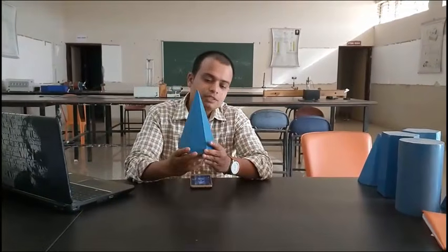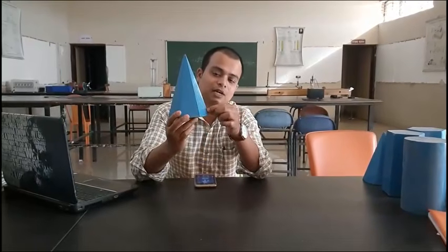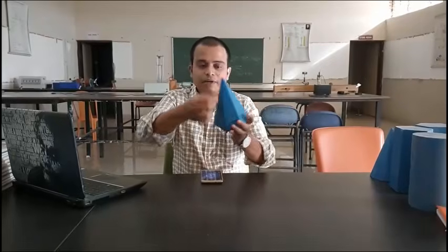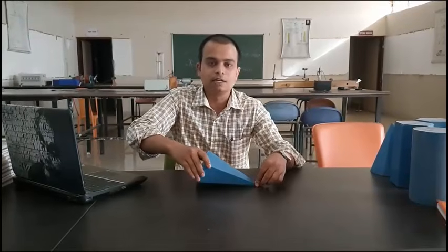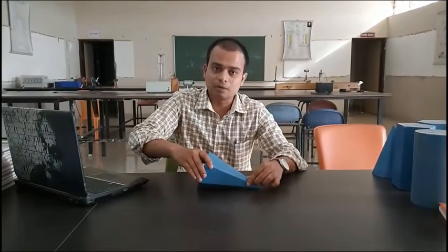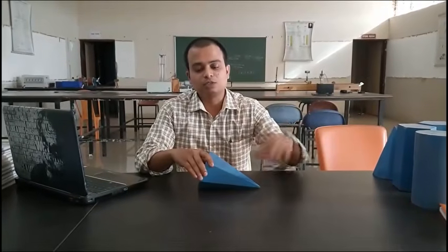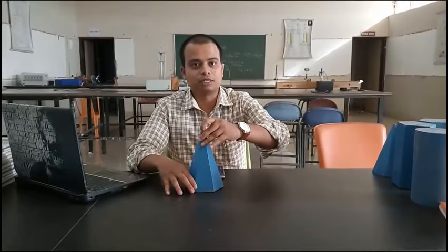And what we need to do is ensure that one of its slant edges remains grounded. That means it remains in absolute contact with the horizontal plane. So out of the 6 slant edges you see over here, one slant edge will remain in absolute contact with the horizontal plane. This is what we need to do in step number 2. Hence, for step number 1, the initial assumption is going to be this.